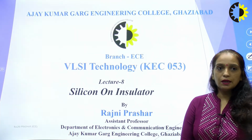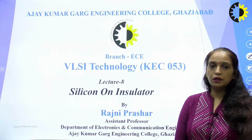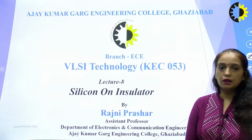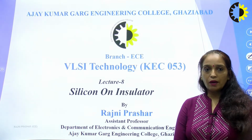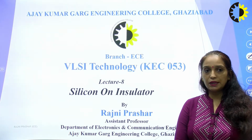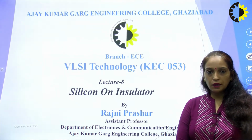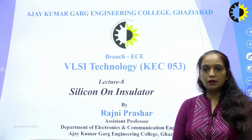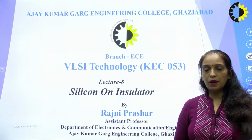Because in VLSI technology we are reducing the size of each transistor, we also have to reduce the dimension of the epitaxial layer. As we go down in technology, we can reduce the epitaxial layer dimension by molecular beam epitaxy.